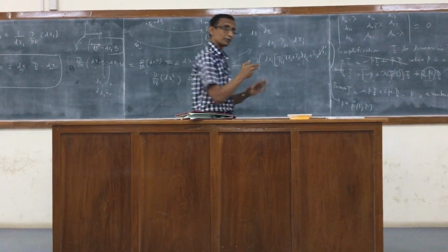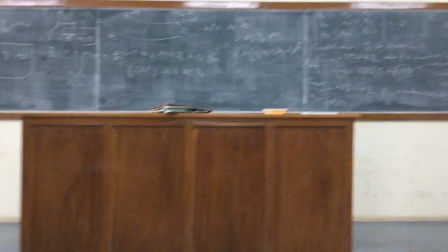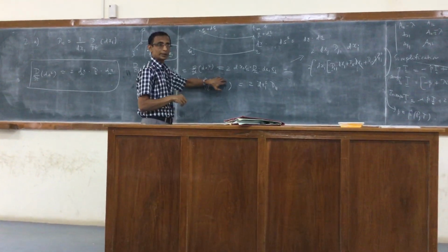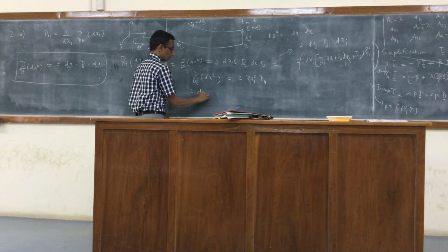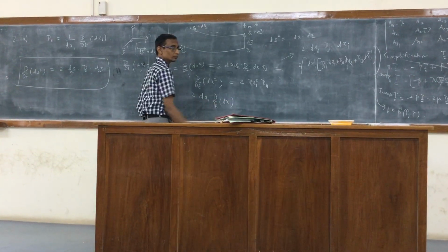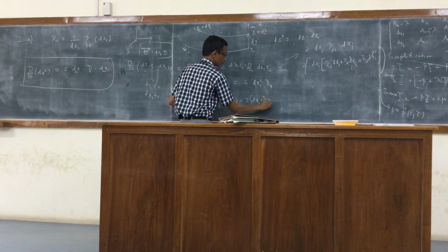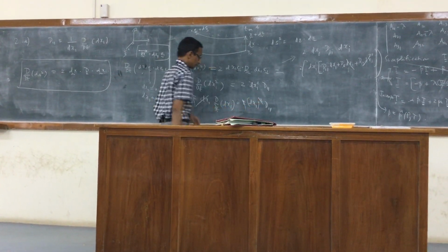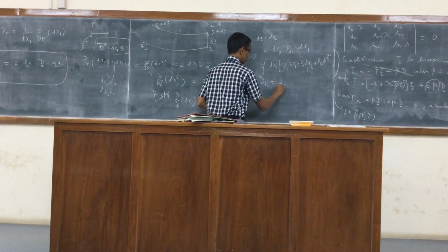You have 9 terms involving all the elements of D. Only D11 will be picked, right? So that is what it is. So d by dt of dx1 squared can be written as 2 dx1 d by dt of dx1, which is equal to 2 dx1 squared d11. When you get rid of the 2 and one of the dx1s, I get this striking relation.